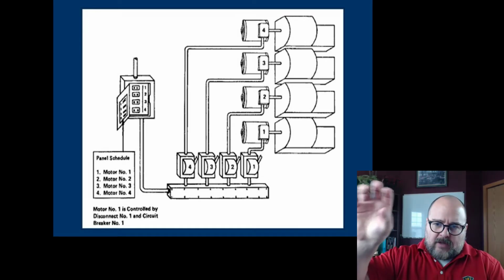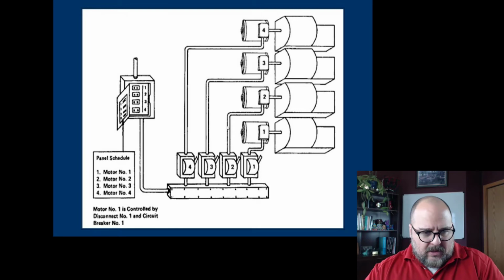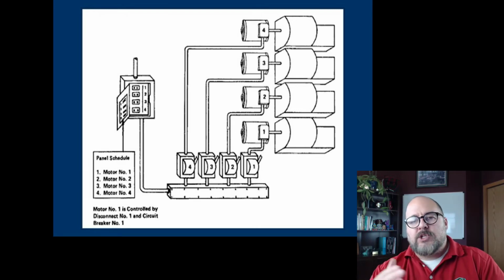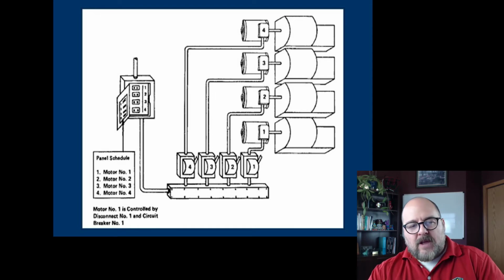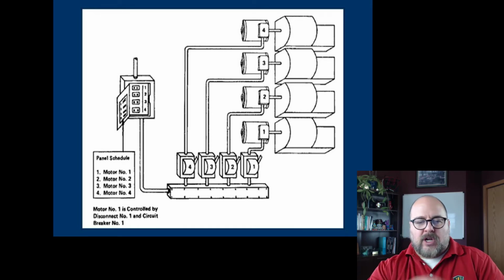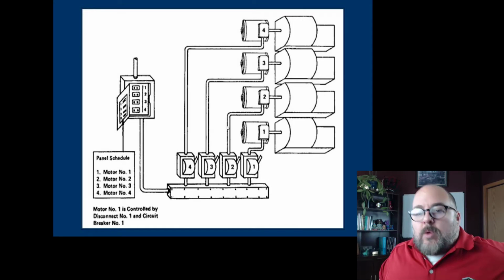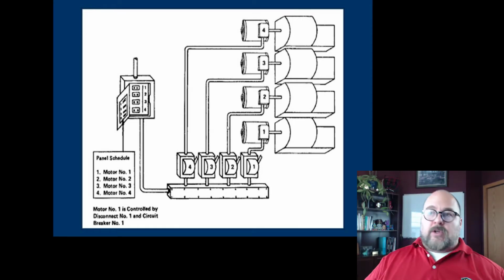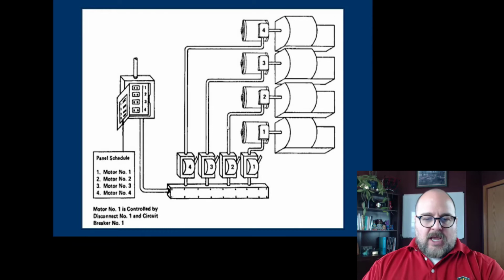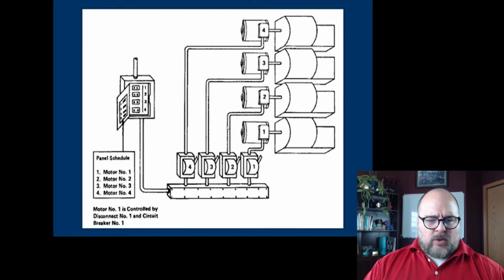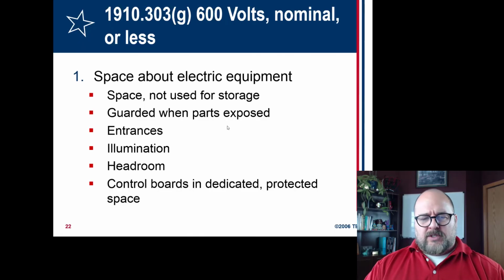What this is showing is just a basic design. Over on the right, you've got 4 different pieces of equipment. They call them motors here. Each one should have an individual shutoff. Because if the shutoff is at the circuit level, you'd have to shut it off, and then all of them would have to be off at once. And usually you just want one down or one turned off so you can work on it while the other 3 are still working. It's a better designed system. Though I don't like the bus conduit there at the bottom. Those are very dangerous because those can energize.